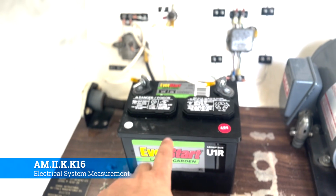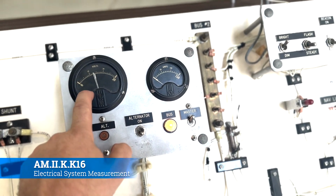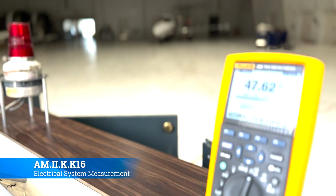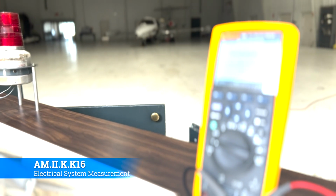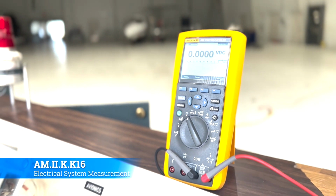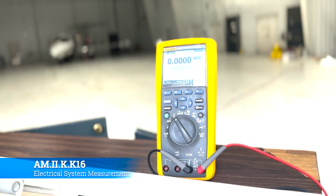All right, so we've reconnected our battery. We're gonna come over here and we're gonna say master coming on. We have power. Our avionics master is coming on. We still don't have a light. Still getting continuity through it. Let's go over and check what we get for power. That's supposed to be DC power. No power going through the light at this point. So now we know we have a problem.